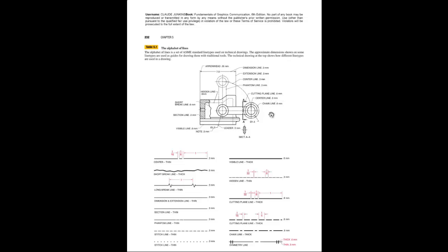It's saying I'm going to cut a section through this arm, and what I see would be shown down here. You can see AA matches up to section AA here. It gives me a cross section with this hatching in it that lets me see what the profile of that arm looks like, because this is the only way to visualize that. If I were to turn this to a front view, a right side, bottom up, I wouldn't be able to tell what the actual size of this is, because it's always going to be hidden behind these objects in any particular orthographic view.